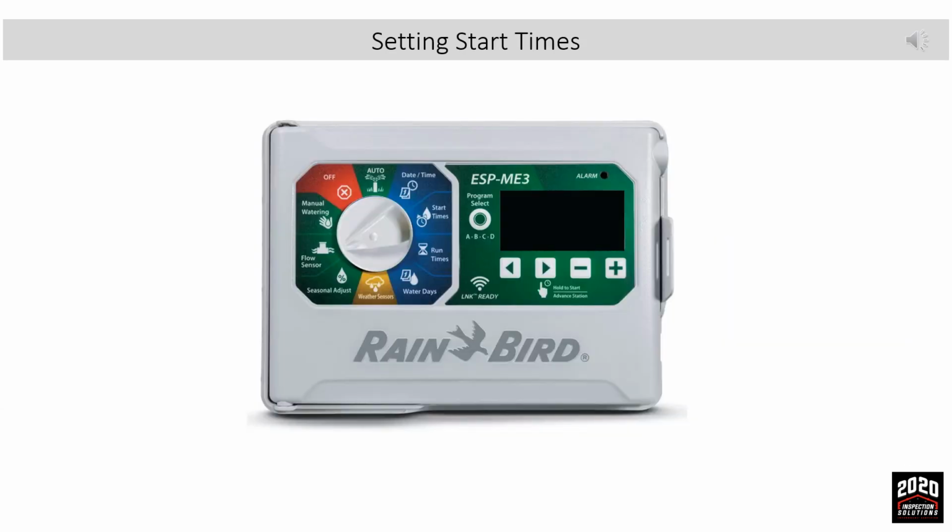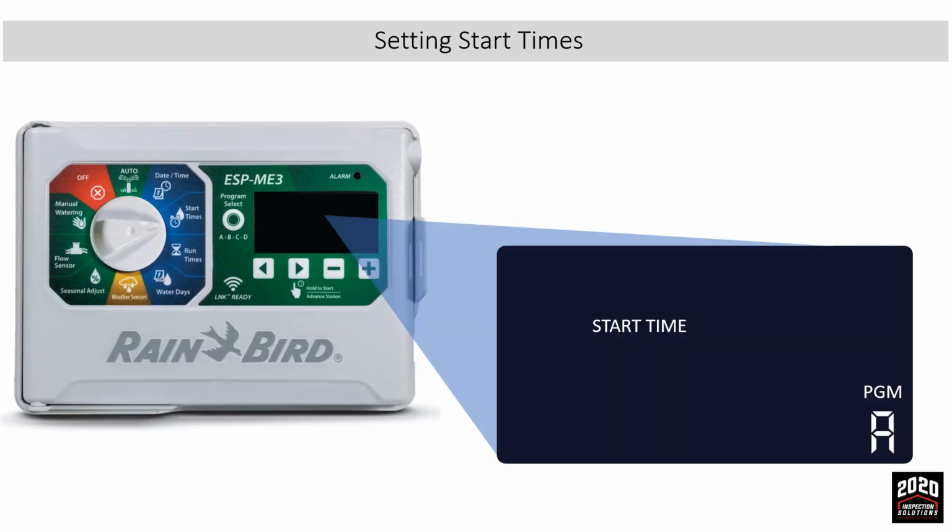Setting start times. To set start times, turn the dial to the start times position. The display will show the first start time for program A. We'll use the plus or minus button and put the first start time to 5 a.m. Since we want to water multiple times a day, we need to use the right arrow and advance to the second possible start for program A.